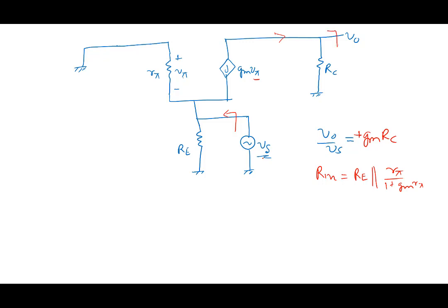R0, since we are talking about the output here, will be basically equal to RC. Right? So we have this circuit looked at from various angles, whether I put the source here, whether I put the source here, I take the output here, I take the output here, all kinds of different combinations that we have done to see what is the impact here.